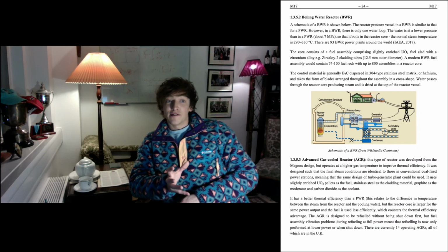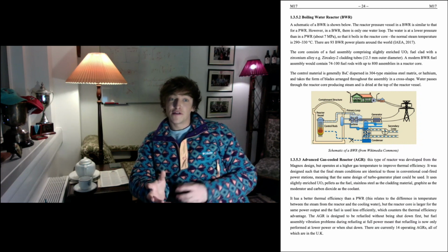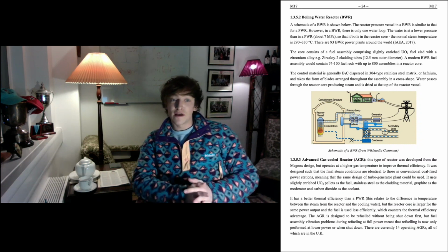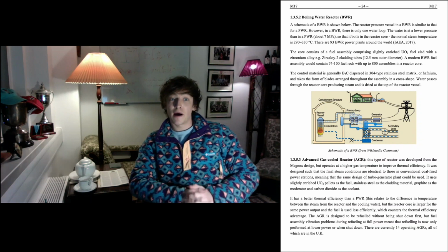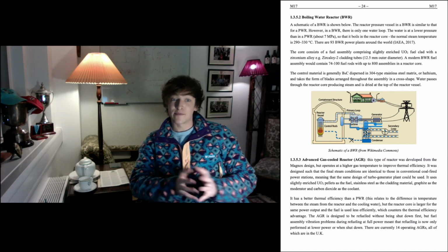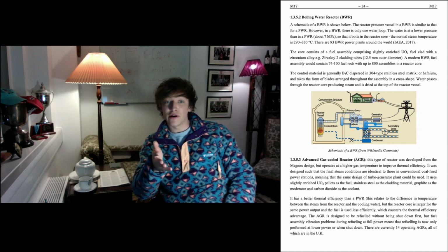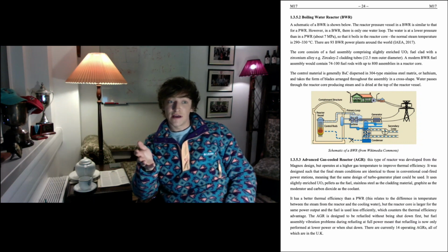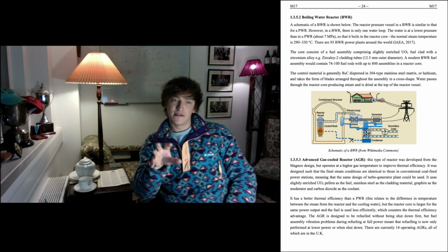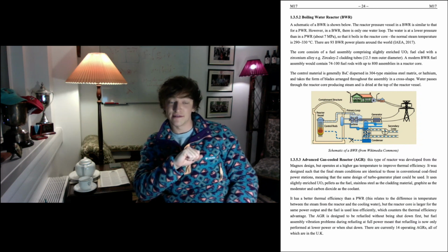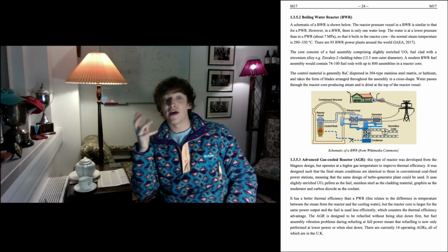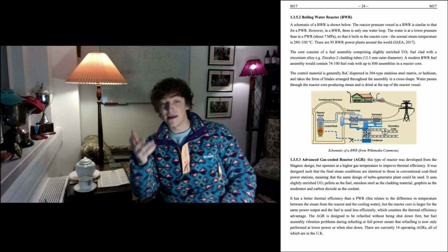And that risk of rupture is further reduced because you've got less piping. If you've only got one circuit, you've got much less pipe length, so less pipe to rupture. Furthermore, you can operate at lower nuclear fuel temperatures, due largely to heat transfer by latent heat of vaporization, which is what you get in the core of a BWR, rather than sensible heat in a PWR.